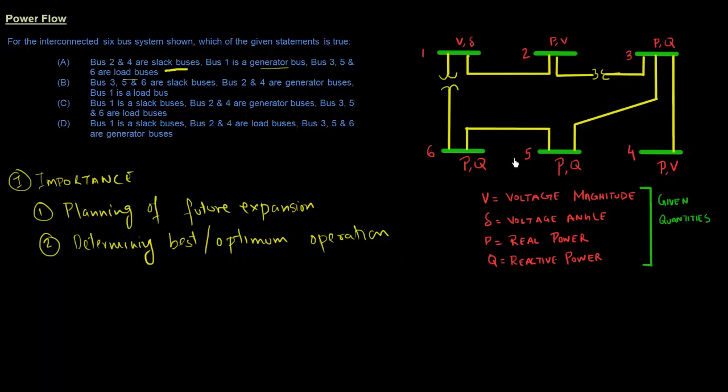It also helps us to understand what would happen if I want to plan, for example, maintenance of this transformer, or if due to a certain fault this transmission line goes away, whether I'll continue to be able to use my existing generations, whether I'll be able to feed the existing load. So if there's an existing system, what will happen to it? It allows us to determine that as well. So that's where a power flow study is very, very important.